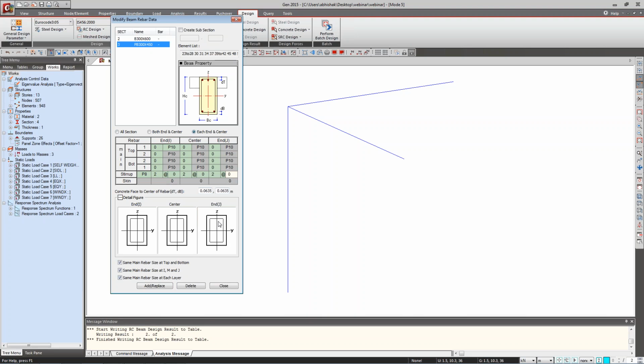Now, one more question is asked by Chetan Safaria: if the column fails, then how can we correct it? See, if the column fails, it is shown in red color. So you have to first go and see the detailed diagram, meaning the detailed analysis results, to see in which form or in which case it fails.